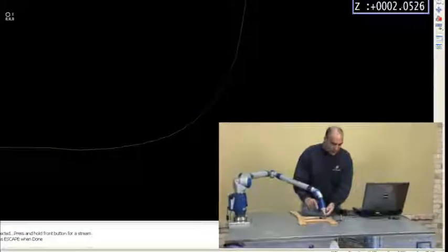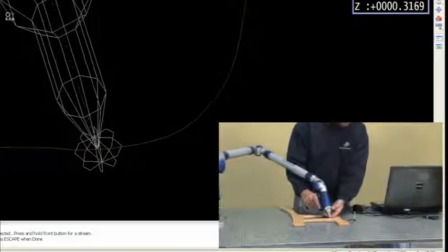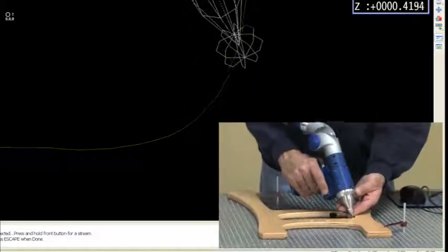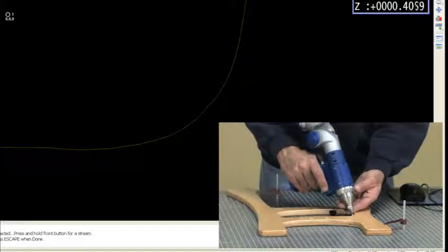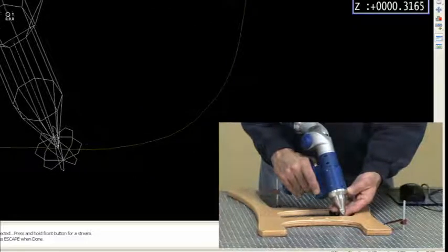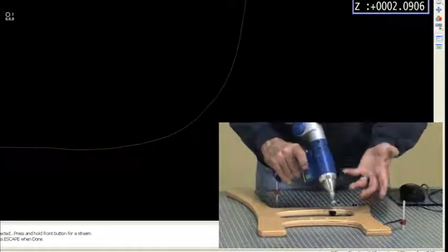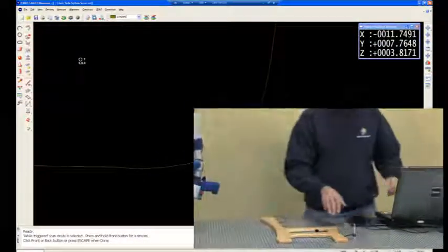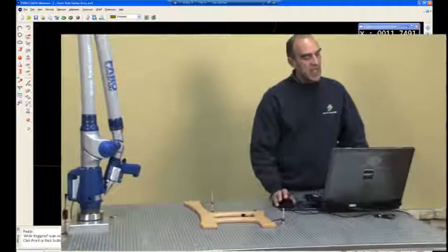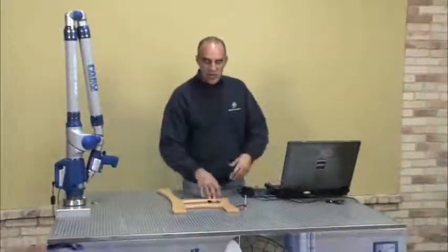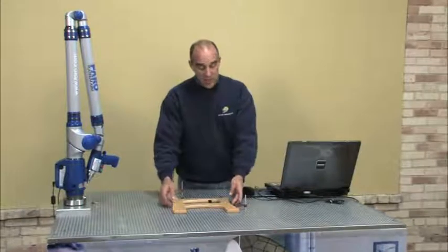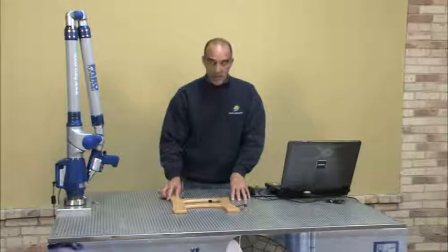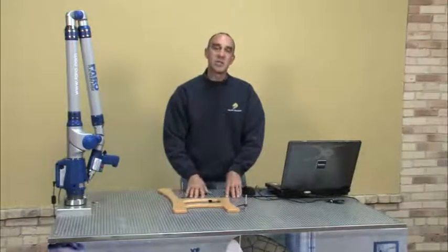So notice on my screen, when I come into that area, notice that that probe is hitting kind of in that middle section as I work my way around there. So I didn't scan the equator of that probe, I was scanning right to the middle of that probe. So that's a good way just to make sure that your scan isn't to the outside of the probe, it's truly to the center of that probe. So just don't forget that when you guys go and export that out. Change the size inside of your CAD file to give it that full perimeter, and it would be 3 millimeters different than what you see here, since I was using a 6 millimeter probe.